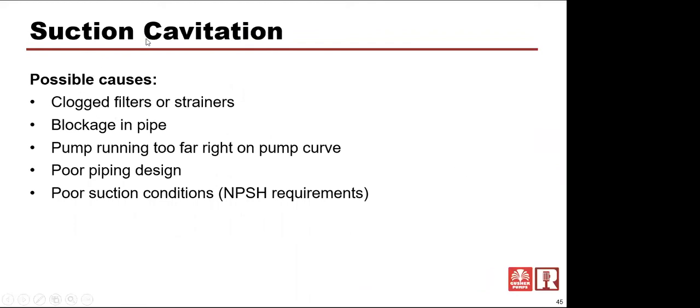But for the moment, let's look at possible causes of suction side cavitation: clogged filters or strainers on the suction side. Remember I said that a suction strainer can be a good thing for you. It keeps big solids from coming into the pump. But if it gets clogged up and restricts the flow, then all of a sudden we can create cavitation inside that pump. Any kind of blockage in the pipe, we've seen cases where a towel or a shirt or a glove gets down into a pump tank and closes off the suction side of the pump. So it's blocking a good steady flow into that pump.